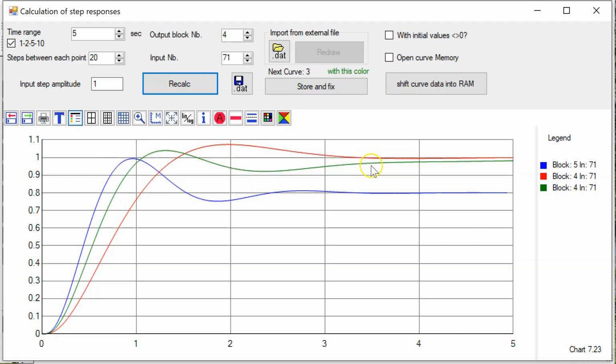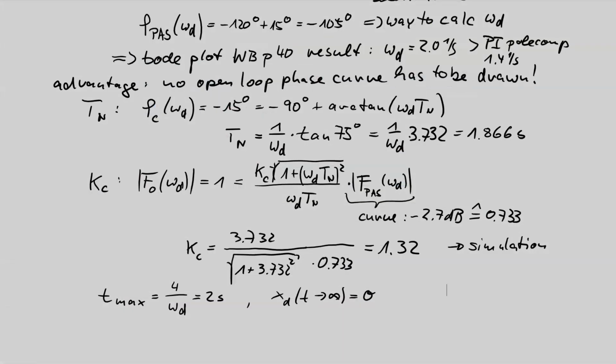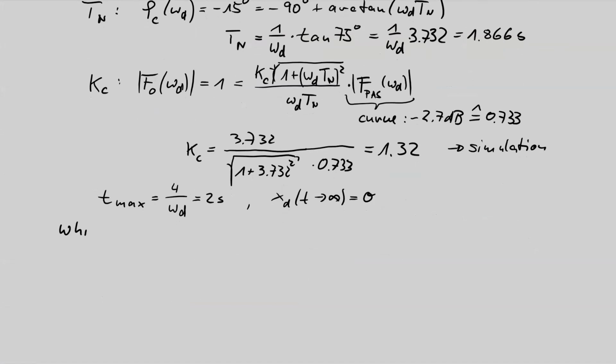Yeah, my question is now, what do you think? Which curve is better? My answer is this depends. This depends on the tolerance range. I will show you that one curve is better if the tolerance range is 5%. The other curve is better if the tolerance range is 10%. Wait for the values. We calculate these values in the next step in this symmetrical optimum design method. So, which PI design is faster?